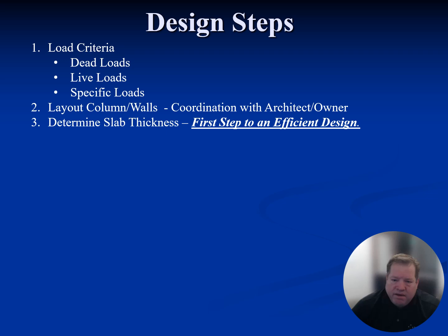The biggest problems I've seen with engineers in terms of design of structures is when the slab is too thin. It should be 12 inches, but they want to be a superhero and make it 10 inches. To do that, you have to add in a lot more strands to increase the pre-compression, and that usually leads to overbalancing. And that usually leads to cracking, potentially some blowouts, and other things that are more detailing issues. The right design is the right slab thickness, plus or minus 200 PSI. If your slab is 300-400 PSI, I'm going to say that your slab's way too thin.